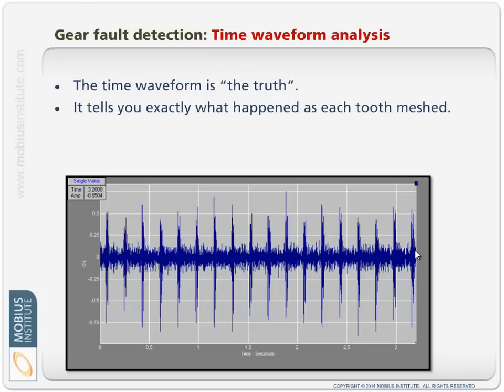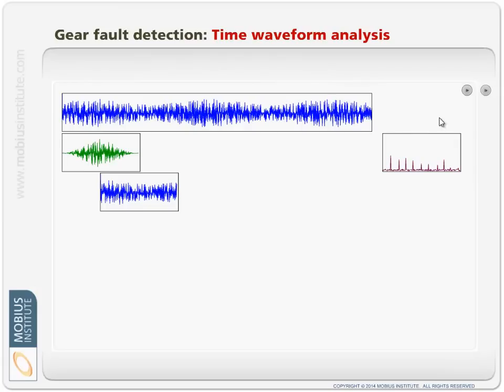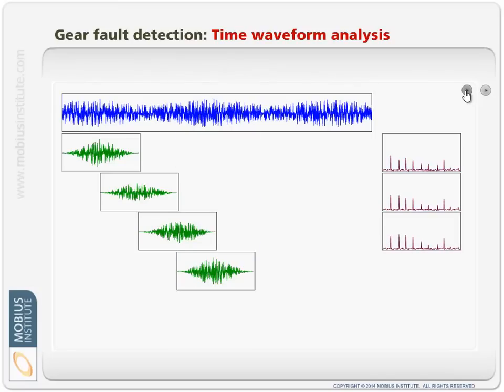But when we get even more complicated time waveforms, or therefore vibration from the machine, the FFT becomes even more limited. What you've got to imagine is we have this vibration just coming from the machine, whatever it looks like, and the analyzer grabs a chunk. The time of this chunk, or this time record, is based on the lines of resolution setting. So it grabs that, it windows it, calculates an FFT, and grabs another chunk, and there may be overlap, and it windows that and calculates another FFT, and does it again, and does it again, and we end up with these 4 time waveforms and 4 spectra, and we average it together.